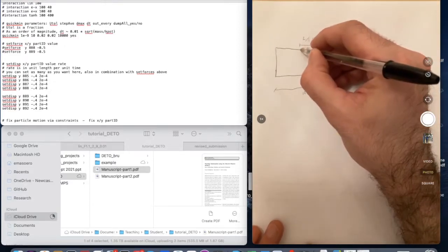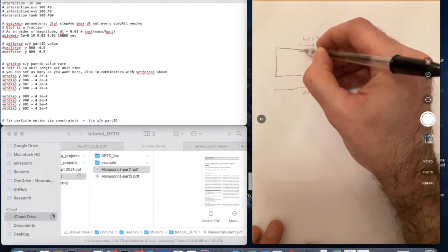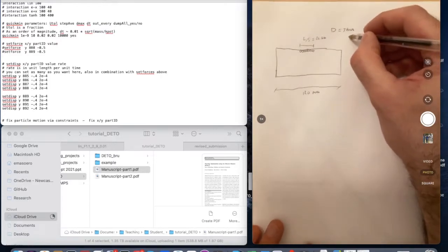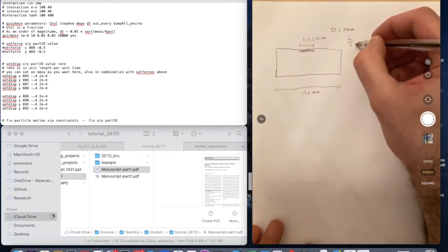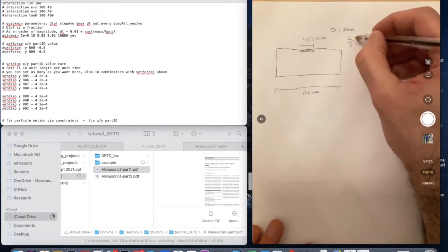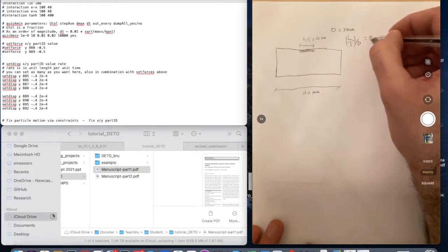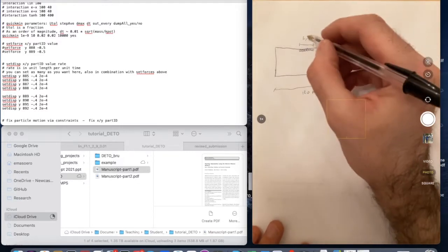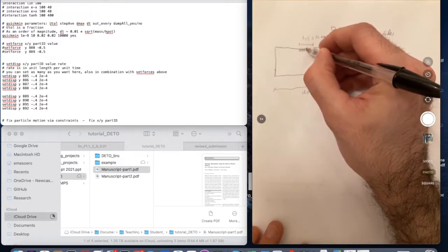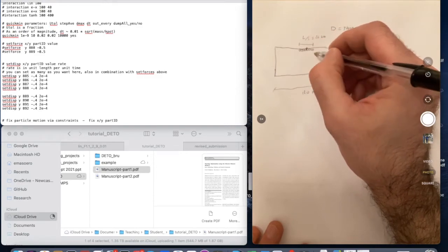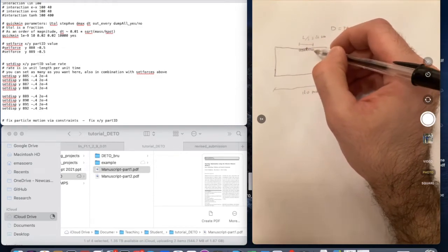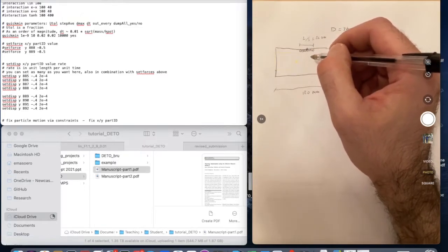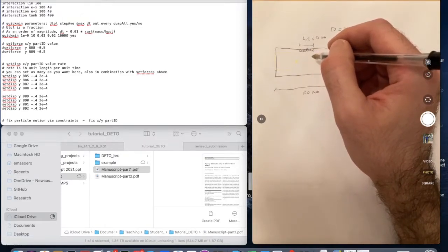So the particles representing the central fifth here will be L/5 over D, which is equal to 8 particles. So what we must do is to pick the 4 particles just before the axis of symmetry at the top and the 4 particles just after that. And to do that, you have to count the particles correctly.